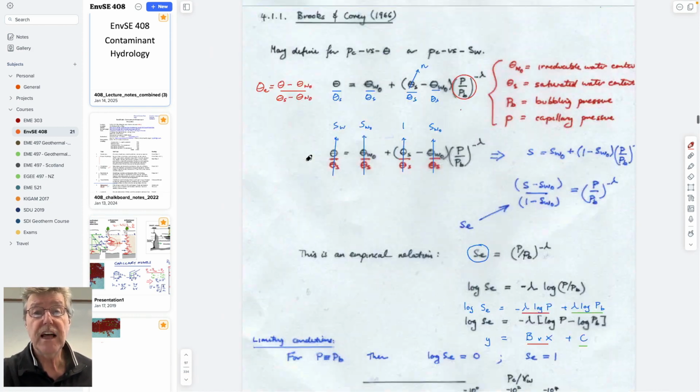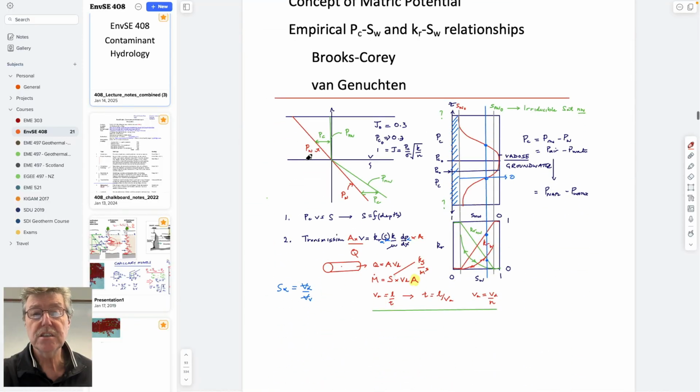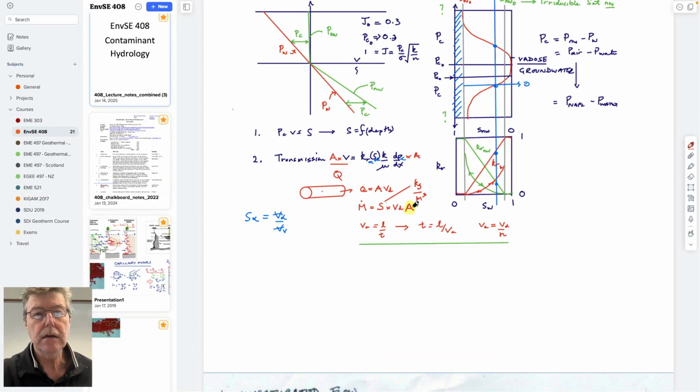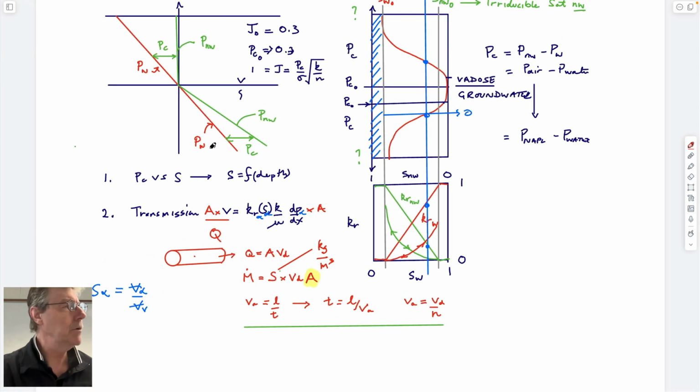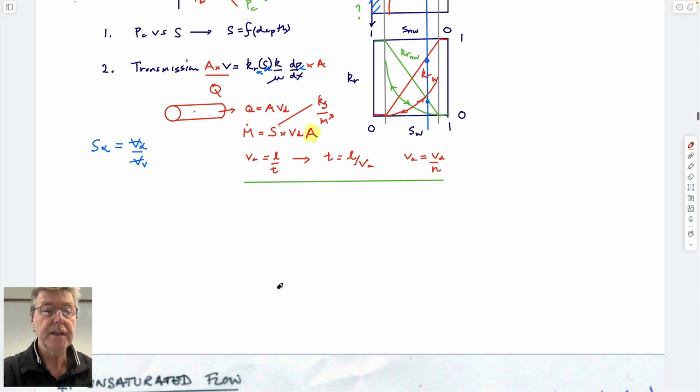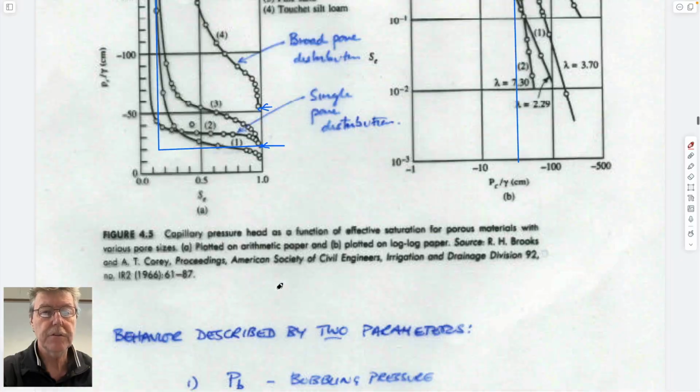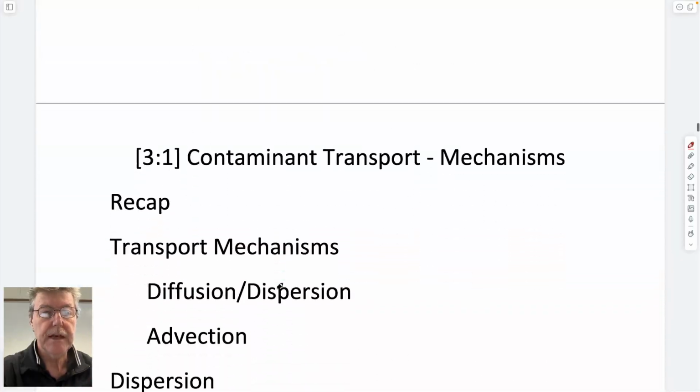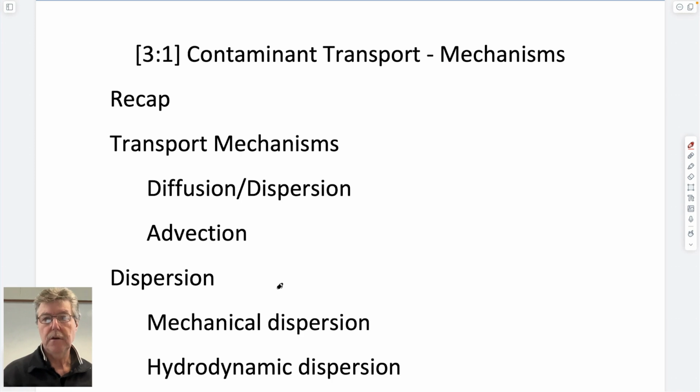If you were taking notes last week, in our discussions last week, we didn't have this A. Sean was puzzled by this, and so this was saturation times Darcy velocity. That gives you a velocity with a concentration attached to it. If you multiply by cross-sectional area flow, it gives you a mass accumulation rate, which is what you've been using in the stuff that you've done. So that was that. So today, and starting for the next 3 periods, a bit noisy today.